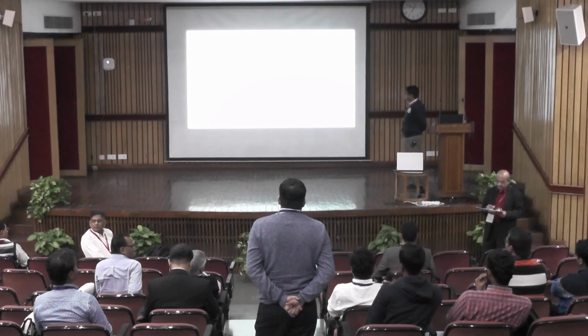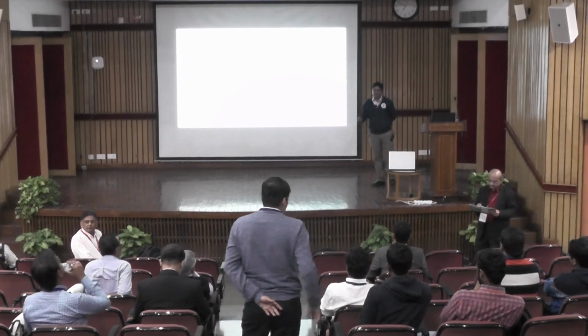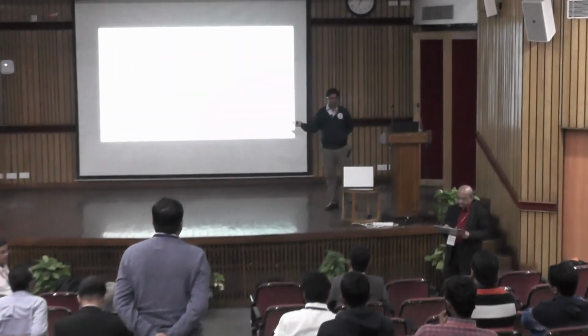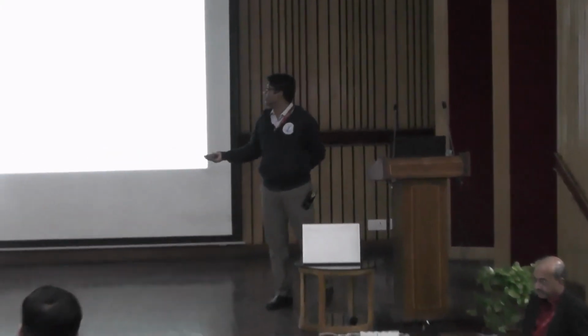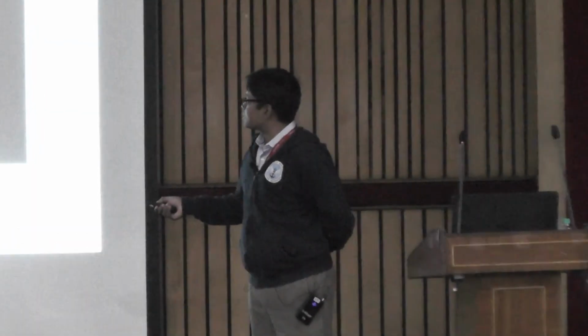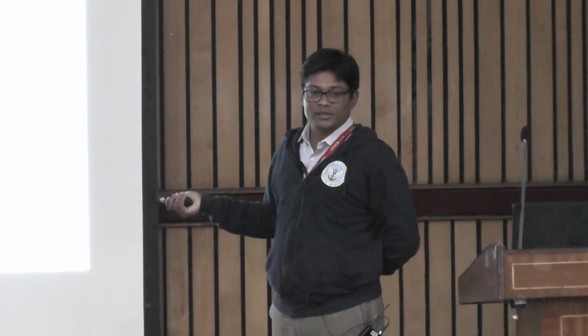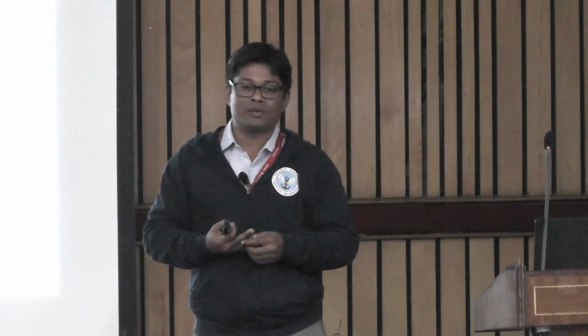Right, so that was the second part of my talk. One possibility is that you can modulate your inlet flow. Let me just show you this setup. This is basically a laminar burner, and here we are not using a speaker, as you correctly pointed out, because you cannot put a speaker in a gas turbine engine. But at most you can put a speaker in the inlet flow, or you can fluctuate the inlet flow. That is exactly what we are doing here.